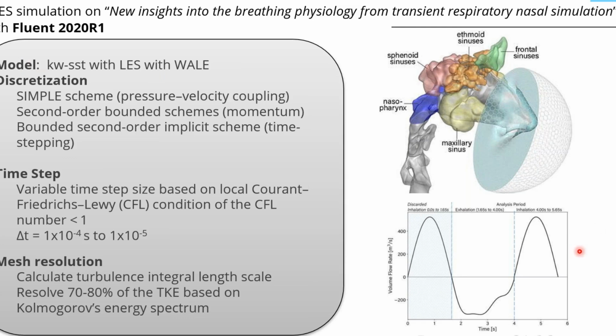The main thing here is to look at resolving the entire flow range, or the flow physics, over the exhalation and inhalation phases. So here we can see that the whole simulation will go to nearly 6 seconds, and we typically discard the first inhalation phase because of startup effects, where the initial startup has a zero state. And so yeah, we discard that section.